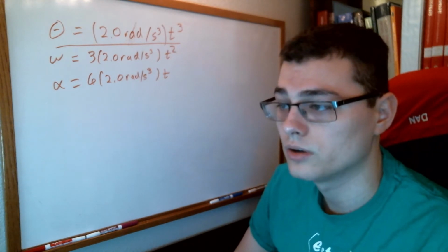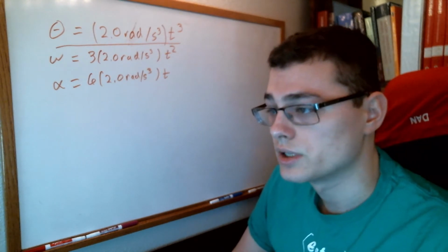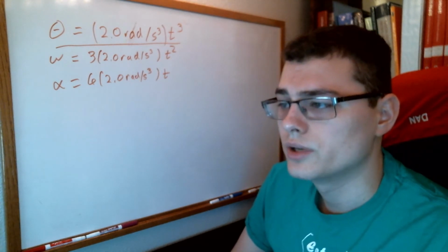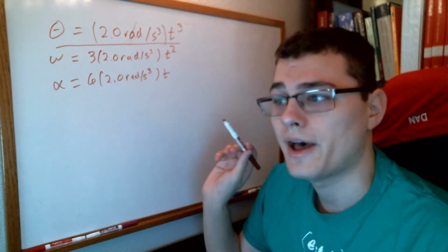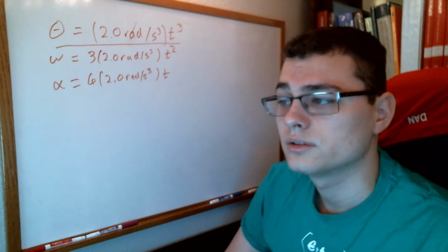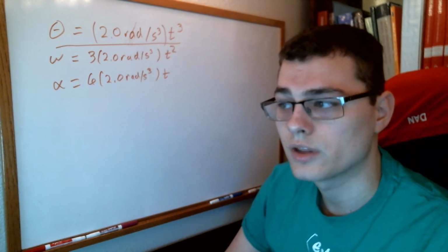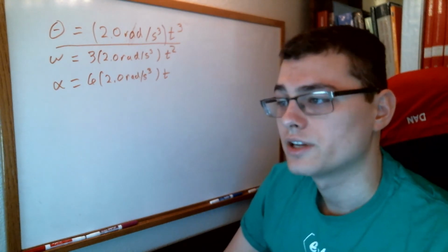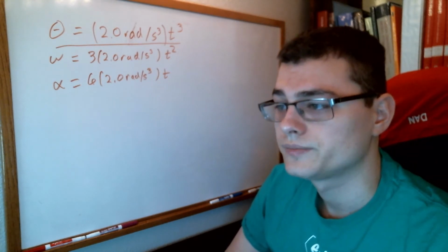And then on top of that, we say, all right, now we have to find the distance that a particle on the flywheel moves over the time interval from t1 equals 2 seconds to t2 equals 5 seconds. What we can do here is take the value at 5 that we got earlier and the value at 2, and subtract those two. From there, we just multiply by the radius of said flywheel, and that will yield us the distance over the flywheel.